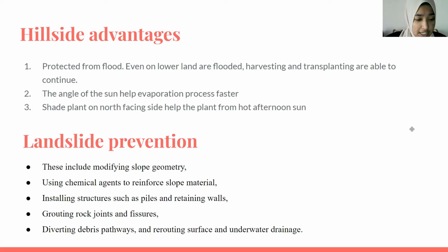If we have enough budget, we can install structures such as piles and retaining walls, routing rock joints and fissures, diverting debris pathways, and rerouting surface and underground drainage.